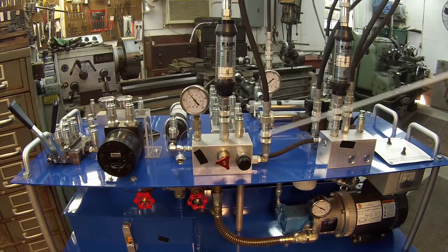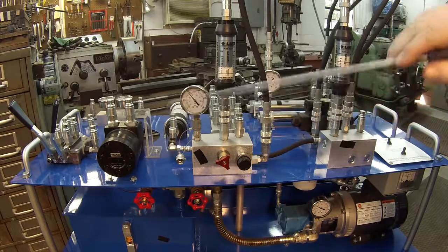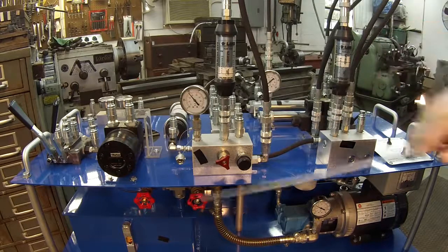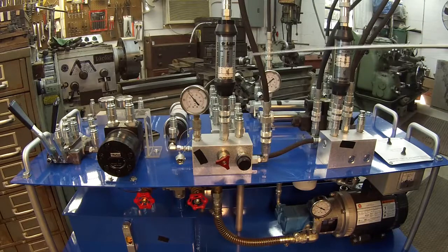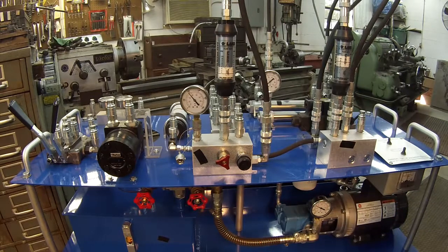All right, same thing with your hydraulic motor. If your motor is turning and it slows down, then you are losing flow in your system somewhere. And again, you see that this pump is pumping 1.8 gallons per minute. If that drops down to 1.0 gallons per minute, that means something's wrong with my pump. So it's very important to understand where your flow is going in a hydraulic system.